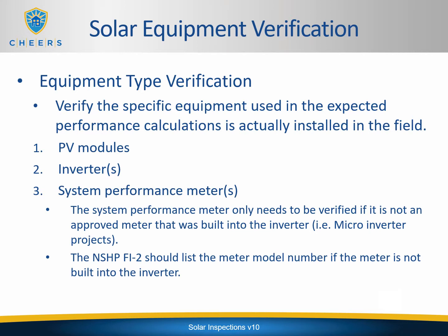Equipment type verification. You will need to verify the specific equipment used in the expected performance calculations, as documented on the FI1, is actually installed in the field. This equipment will consist of the PV modules, the inverter, and the system performance meters.